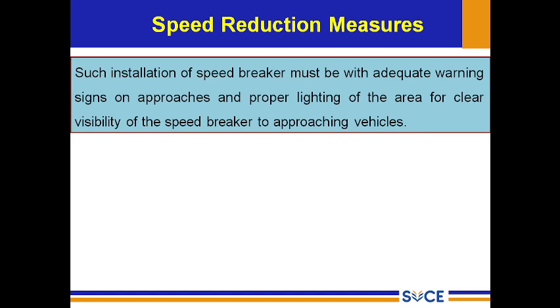In IIT Madras also, they constructed different sizes with different chord lengths. The speed breakers were designed, and finally they decided the chord length should be well enough for a smooth circular curve speed breaker, which gives a very smooth jerk and very little inconvenience to the road users. There are different types of road humps based on the shape: circular humps, trapezoidal humps, and sinusoidal humps. Based on the requirement, these can be used.